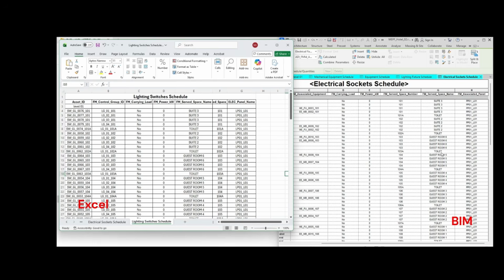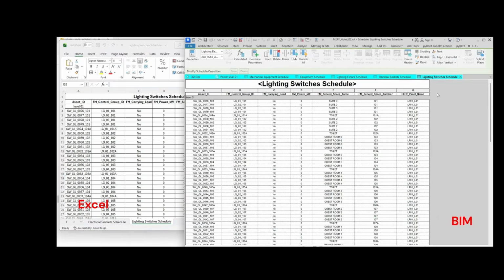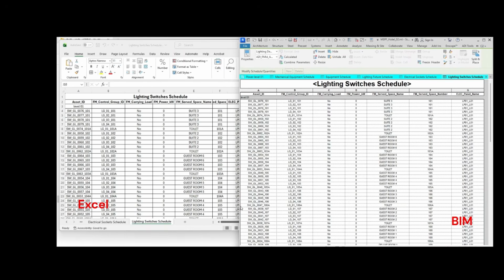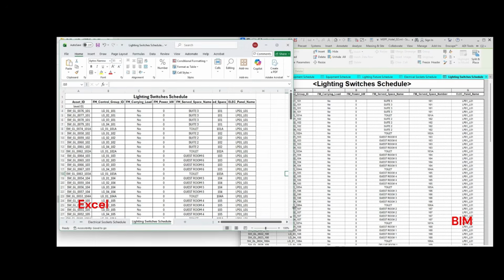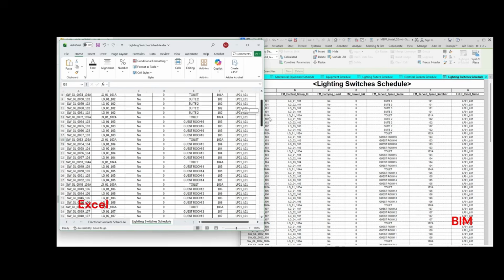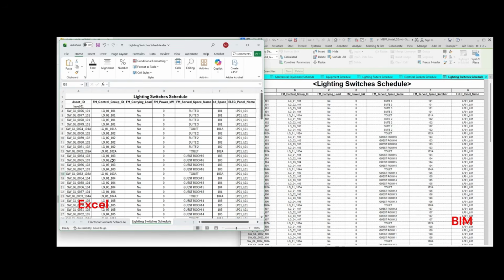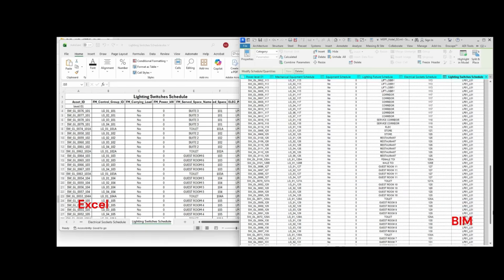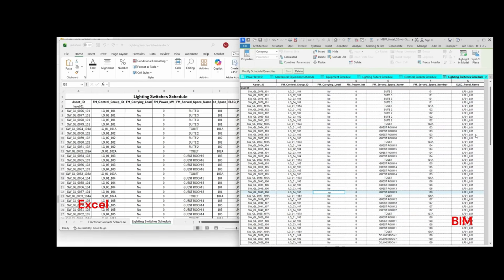Panels, FM view. For facility management, we model electrical systems only up to panel level. Panels exist. Panel capacities exist. Load strategies exist. But detailed circuiting does not. Why? Because panels and circuits can be designed, modified, or rebalanced later, without changing asset-level FM data. Panel ratings here represent available capacity, not final electrical design. This keeps the model flexible and future-proof.